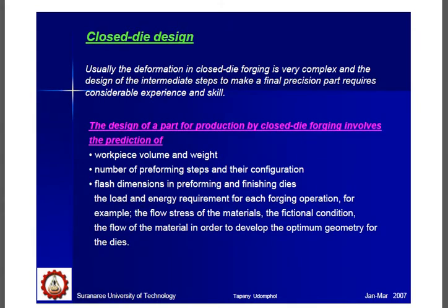Closed die designing. Usually deformation in closed die forging is very complex, and the design of intermediate steps to make the final precision part requires considerable expense and skill.